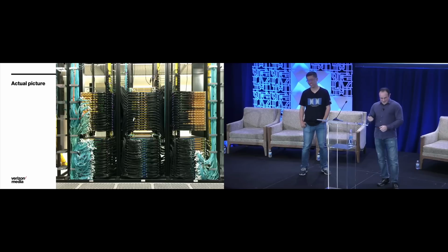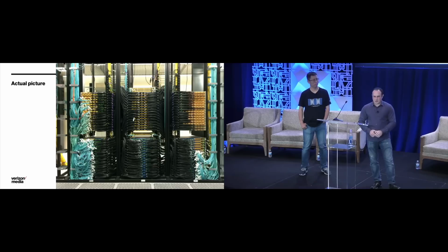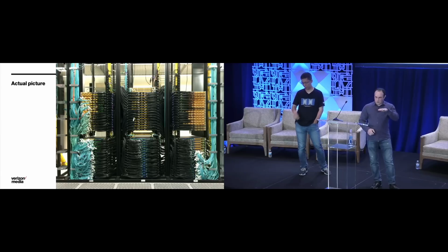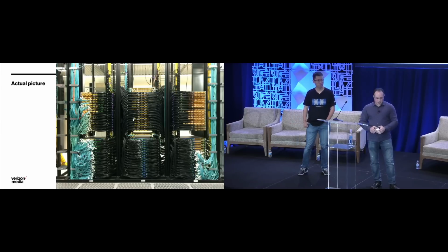Now, needless to say, we solved this. What you're actually looking at is what's in production. This is 2 separate VCs. One is from cluster A, one is from cluster B, one on top of each other, essentially. As you can see, we've spent quite a bit of time designing custom length cable bundles to make miswiring incredibly hard, because the cables are actually designed with less than a 2.5-inch tolerance. So when we pull something out, they almost stay right in place, and it's really hard to miswire.